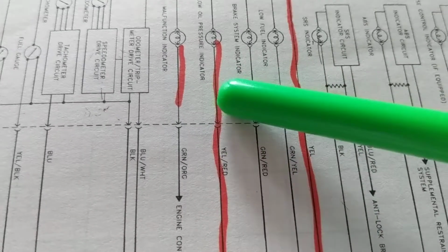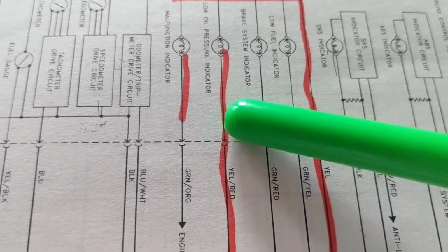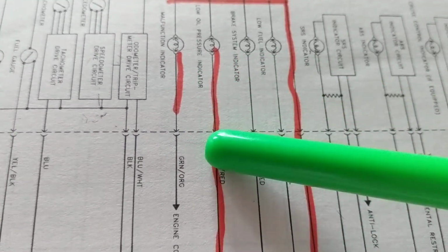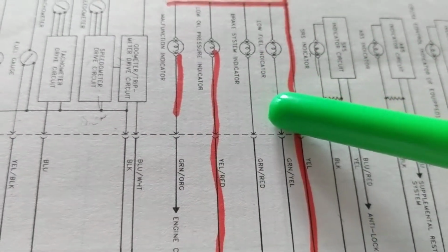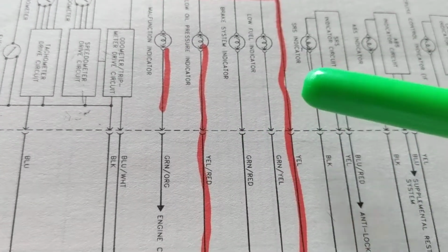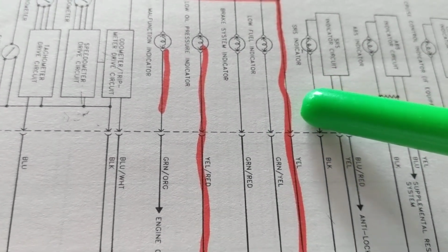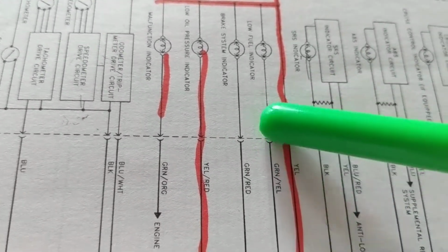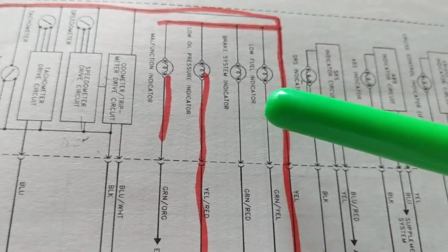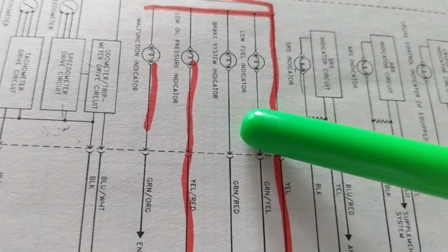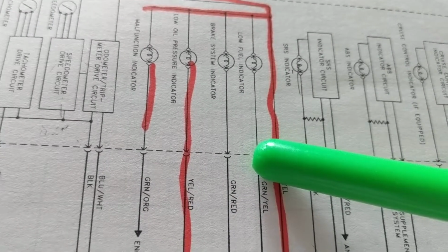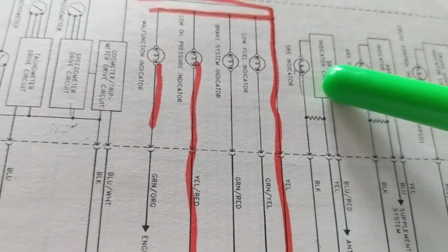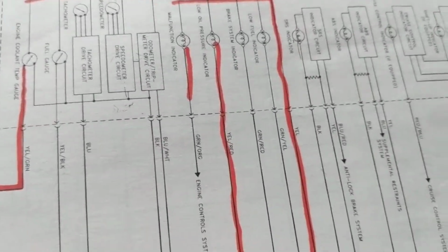The computer is monitoring everything, every single thing once you turn on the key. Even before you turn on the key, the computer controls everything. And it sees and it says, okay, engine is not turning. I'm not going to let the fuel injectors allow fuel into the cylinders. I'm not going to allow the ignition coil to fire a spark. There's no reason for it. But the computer doesn't know that the camshaft sensor is bad or the crankshaft sensor is bad until you figure it out yourself. Right? It just sees no signal from those sensors. Can't turn on the engine. No reason for it.